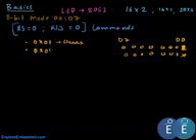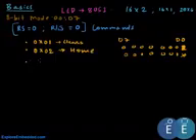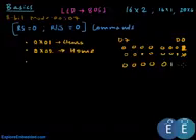Okay, so this would be 0x02 or 0x03. So this gets the cursor to home. Now the next command sets the entry mode, and this we discussed in depth in the first 2 basics videos. So for this, the command would be all zeros, and the one shifts here.